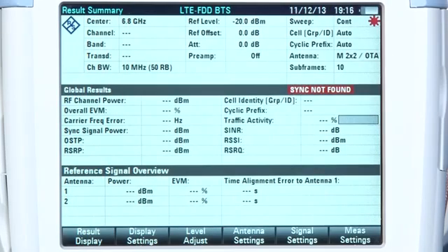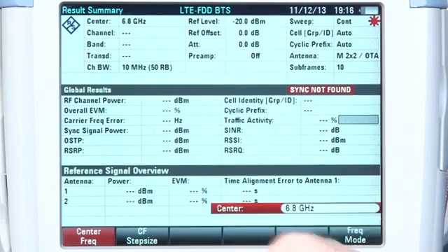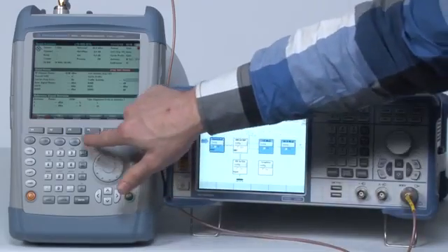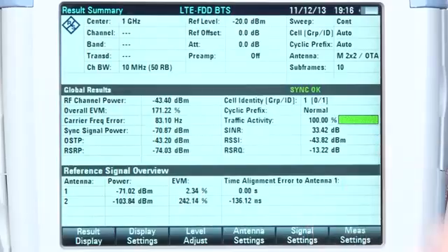Now we can select our measurement frequency, in our case 1 GHz, as we are simply using a generator. Next, we should hit level adjust to adjust the front end of the instrument to measure the signal appropriately.